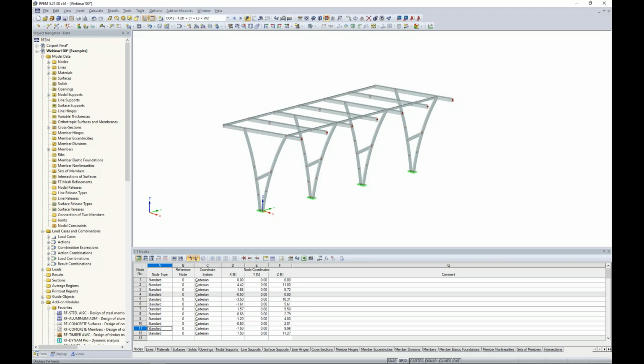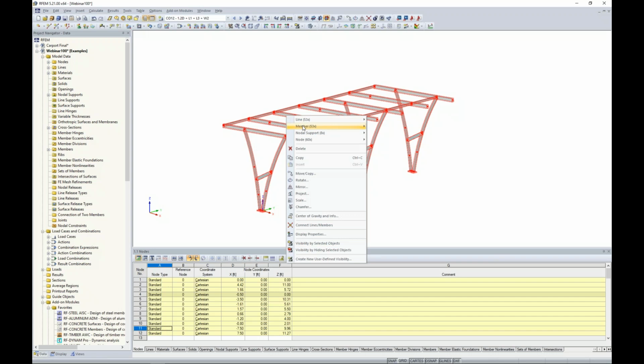Additionally, there's a 0.8 factor that should be applied to bending and axial. And lucky for us, these requirements are almost identical to what the AISC requires. And what we have in the program, when we highlight all of our members, we can right-click to edit the